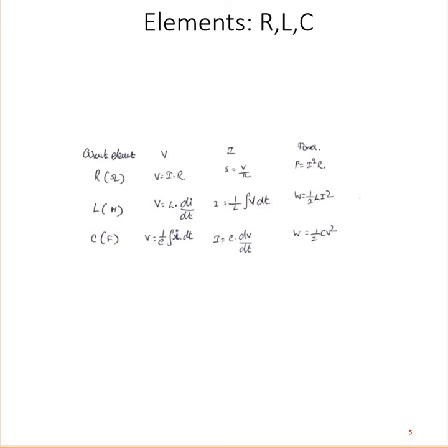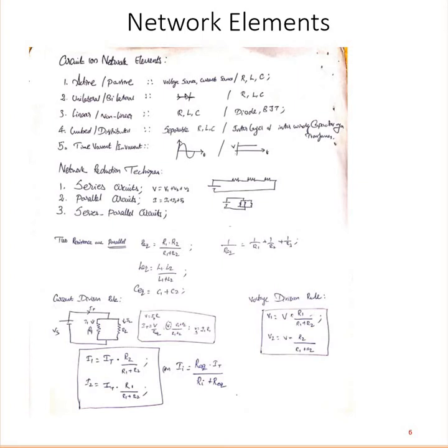That's all. But if the voltmeter place is replaced with the ammeter, the circuit will get affected. It will spoil the circuit. It will be short circuited. Be careful. Okay, that's why it's both opposite.